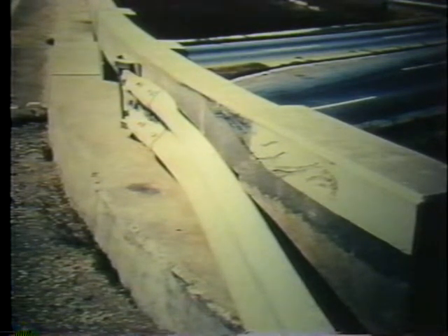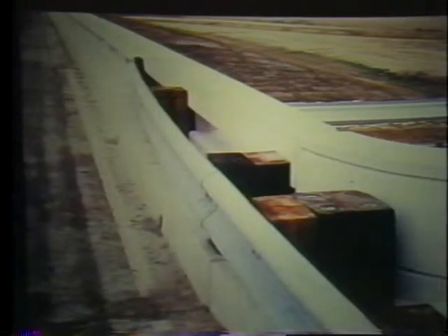The approach rail should be blocked out flush with the outwardmost projecting part of the bridge rail. In this case, the approach rail should be flush with the front face of the raised walkway. Blocking the approach rail out to the front of the concrete safety walk protects against impact with the corner of the walk. This approach rail is well anchored to the bridge rail section for good beam strength continuity. Unfortunately, the rail is lapped incorrectly.